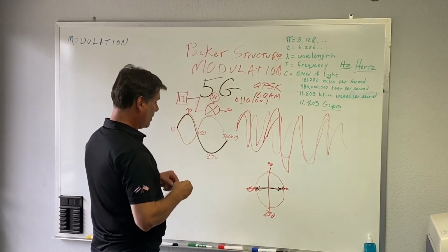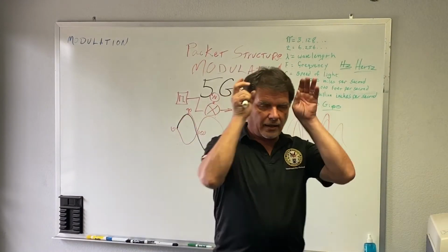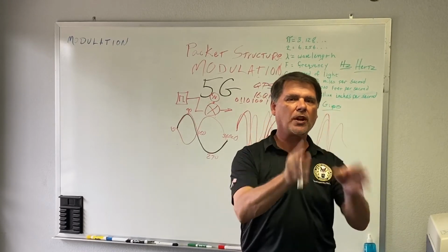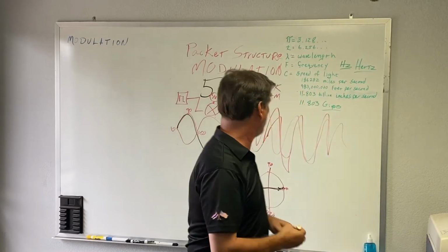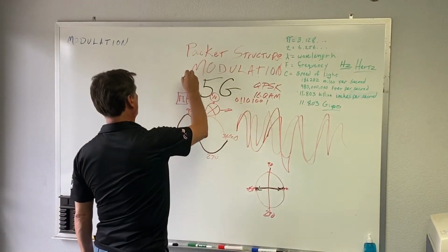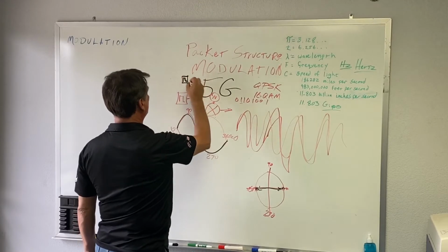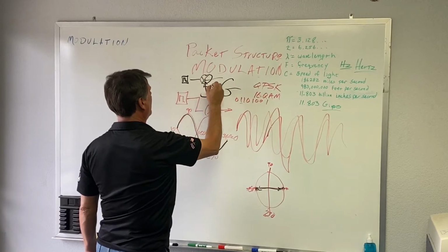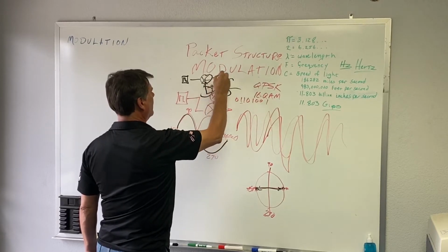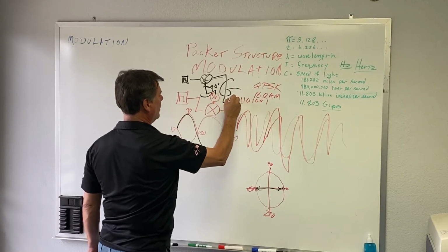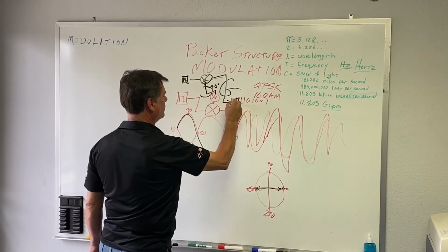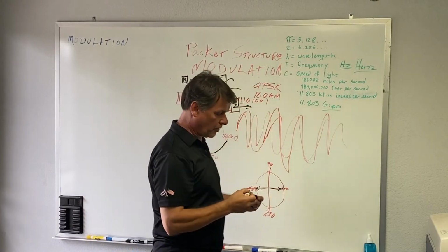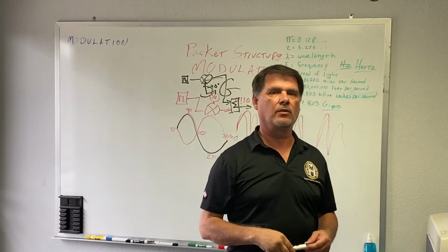Now, you don't get a lot of data through like that. That's not really very bandwidth efficient. That's not an efficient way to use that pipe. You could push more data through that pipe if you wanted to. So if you up level a bit and put a second data source in to a second mixer using the same source shifted by minus 90 degrees, take that output and mix it with this output, you get a single output which produces a QPSK signal.